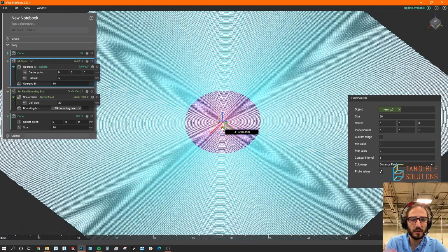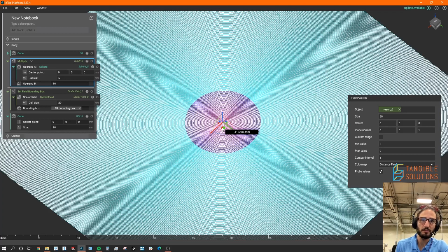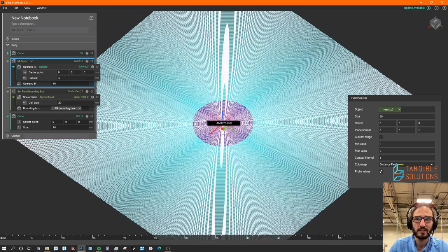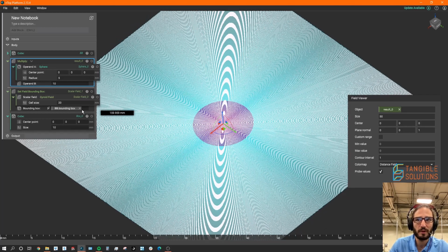And the reason this is important is because when we talk about ramps, we're trying to ramp to and from a particular portion of an implicit body, we're trying to ramp from a point, from an axis. We can very discreetly control the gradient, how that goes and flows to and from the body itself. We can alter the gradient. You can do some of this stuff at the ramp level, but a lot of the times I like to control it at the gradient level because then I'm very distinctly aware of what's happening to my implicit bodies. And that gives me, again, a lot more power and control